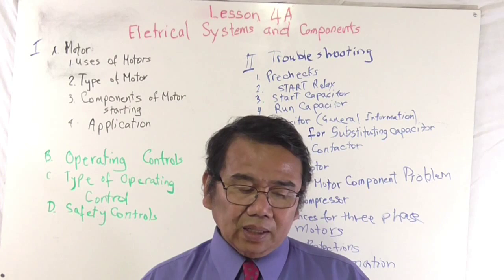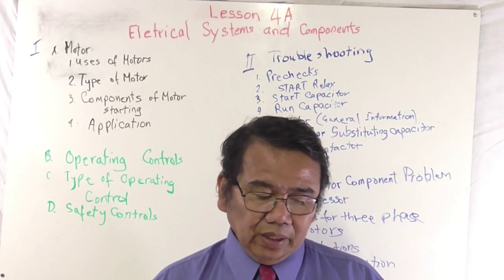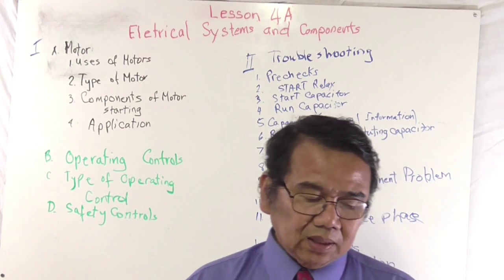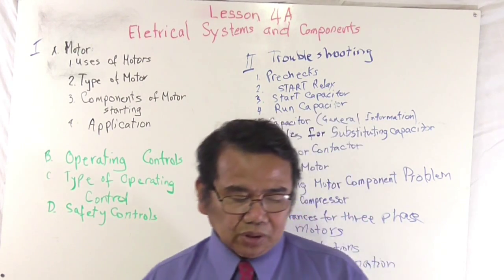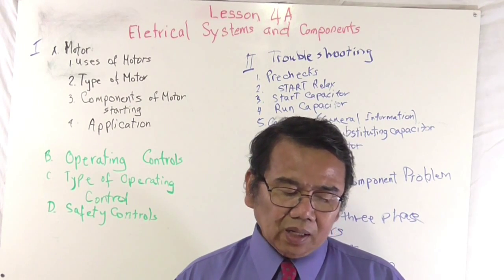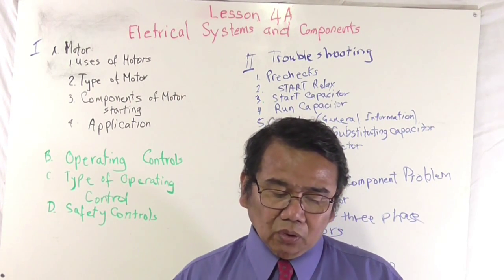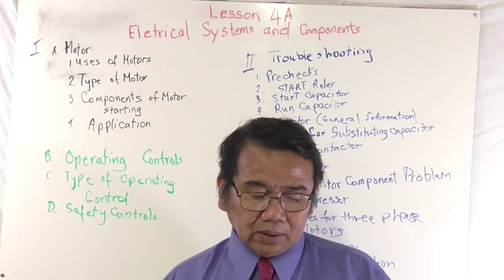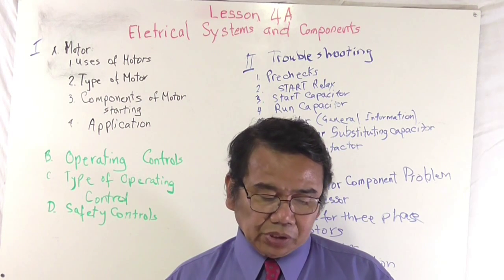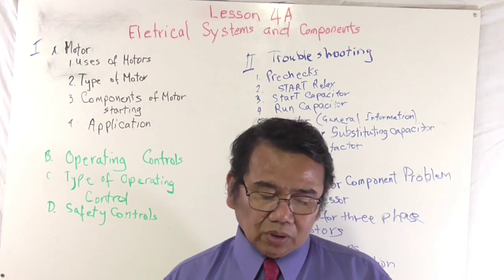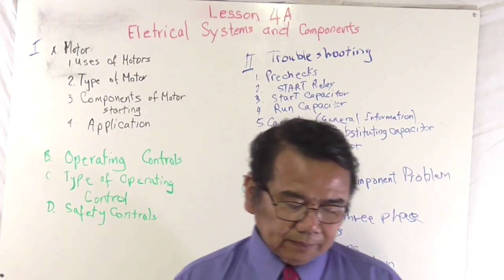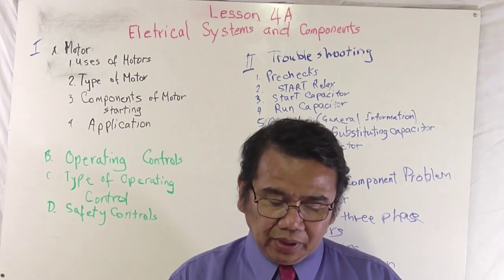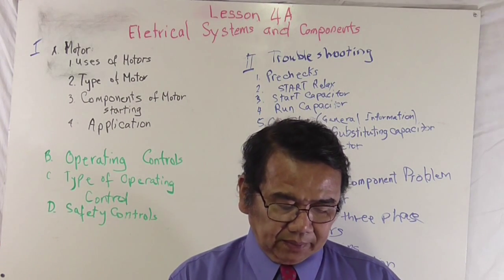Capacitors are usually wired in parallel when needed. Total capacitance is the sum of both capacitors. Only 1 horsepower and larger use a 15,000 ohm to 20,000 ohm, 2 watt bleeder resistor wired across the start capacitor terminals. It prevents excessive relay contact arcing.